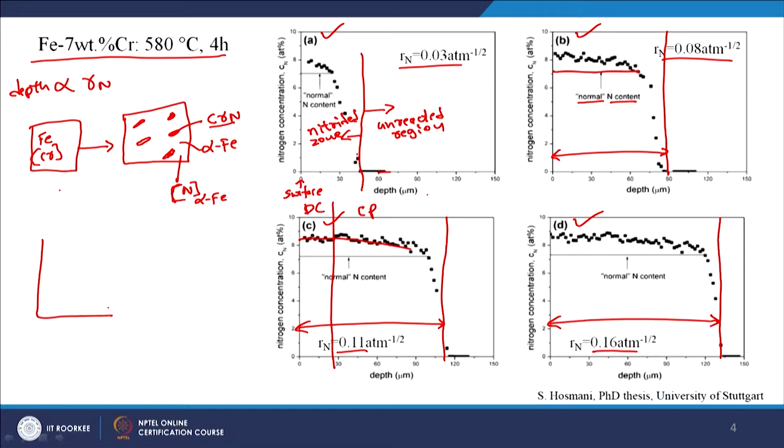as if we look at the Gibbs energy, if we plot the Gibbs energy of alpha iron as a function of nitrogen content, for example Xn, going from some concentration, and somewhere here you have the 100% nitrogen axis, for example, and now you have some trend for the Gibbs energy curve. Okay. And now, if we say that this is the 100% nitrogen axis, for example here Xn equal to 1, and here it is 0, this is pure iron here.